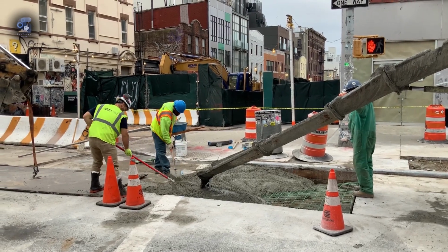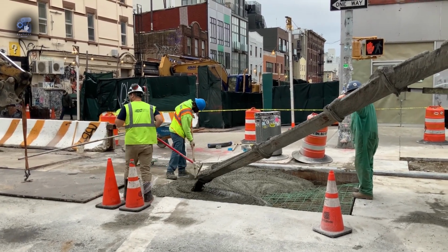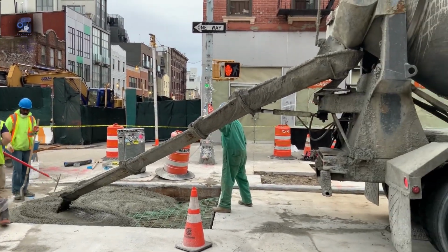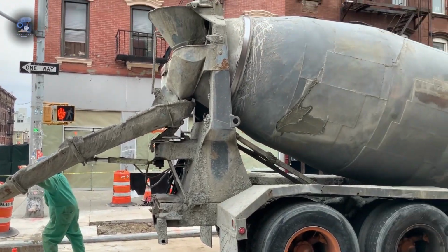There are other advanced geotechnical engineering methods that can be used to improve pavement foundation strength and stability, from the use of stone columns and micropiles to transfer loads to deeper soils, to the use of geosynthetics between structural layers to increase the shear strength and the bearing capacity. But these are topics best suited to be covered on their own in a separate video.